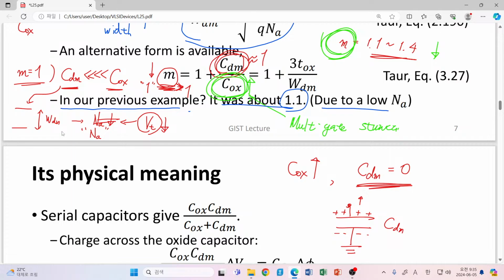And it was possible because here we have quite a thick layer of p-type silicon, so we can supply our negative charge or positive charge just by moving holes. These holes can be attracted or just repelled slightly, so they can provide certain capacitance.